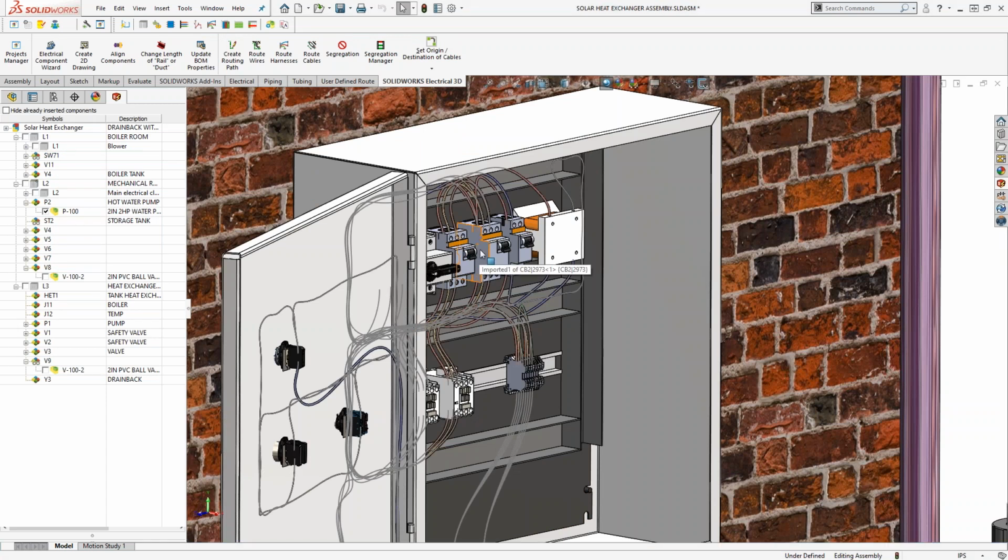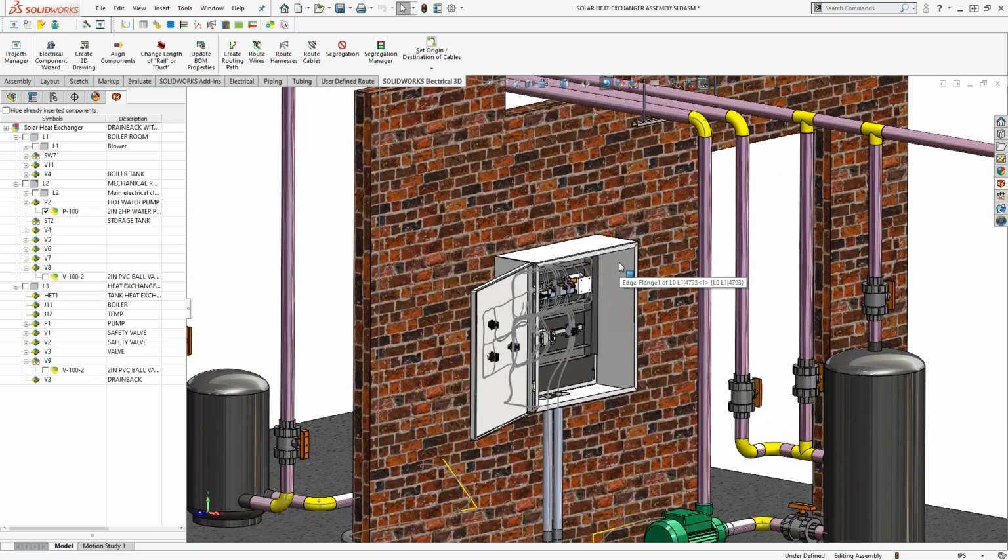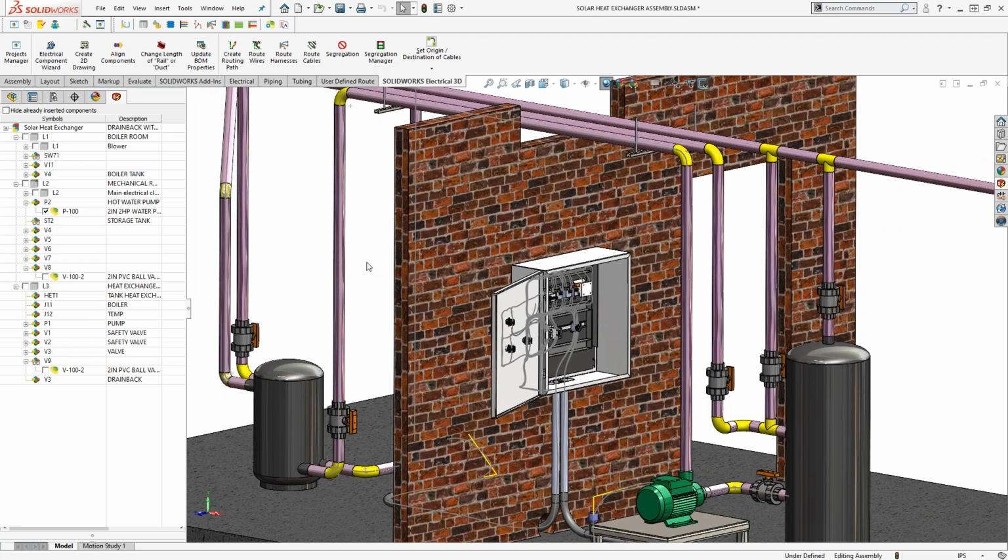Those connection points, C points that you might see in the routing library manager, are built in as features into the feature tree of that part. So once you put them in, you never have to touch them again. They're saved to the part. So if you have a very specific manufacturer part, you won't ever have to touch them, which is nice. As far as the mechanical information on the electrical side, it depends on how you have that.